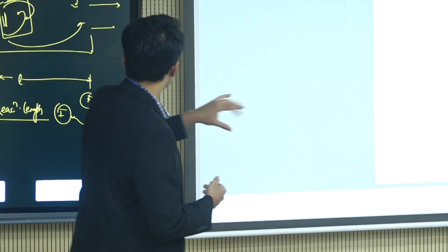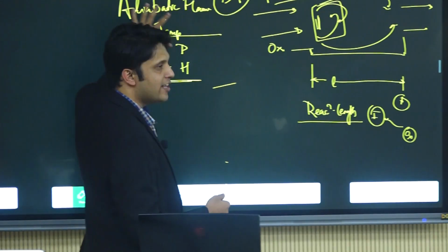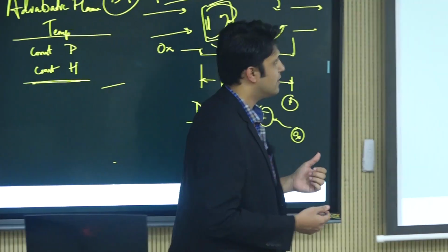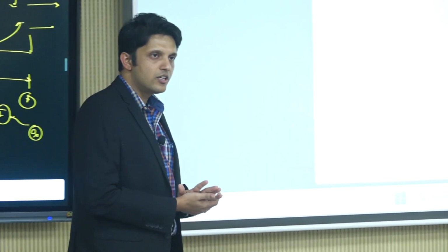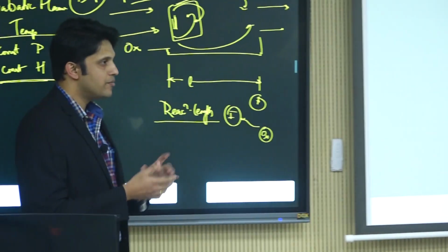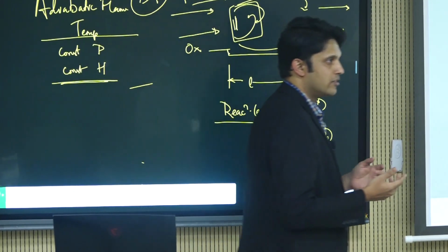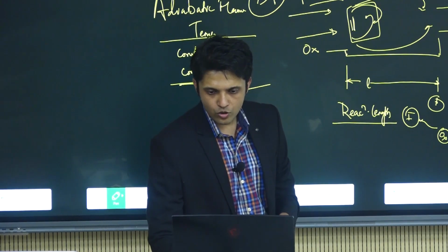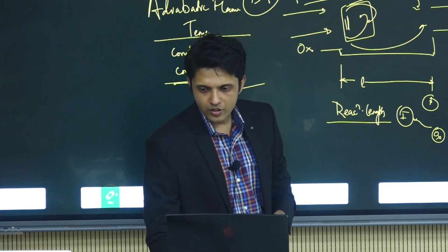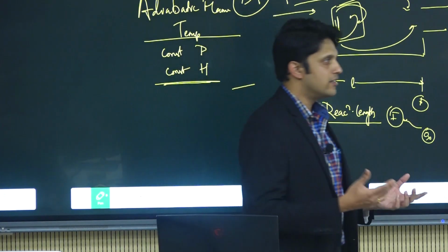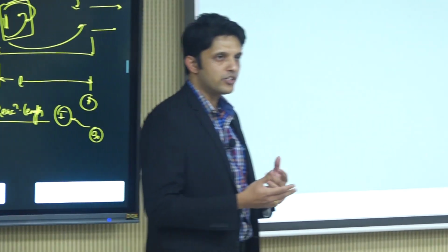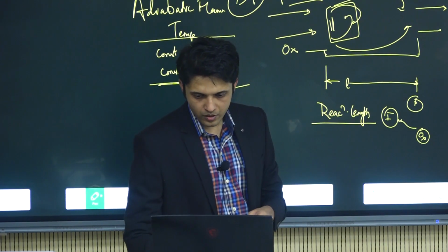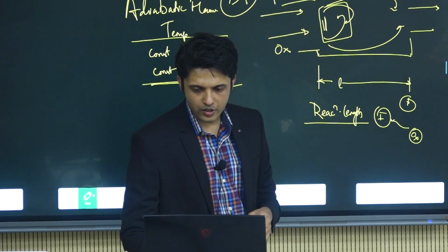So this is a process in which we estimated adiabatic flame temperatures at 1 atmospheric pressure, with an initial temperature of around 298 Kelvin, and a stoichiometric mixture, right, 1 mole of methane and a stoichiometric amount of air. So what happens if we change it? It does not have to be the same equivalence ratio mixture, right? It could be a lean or rich mixture. So let's try a rich mixture.